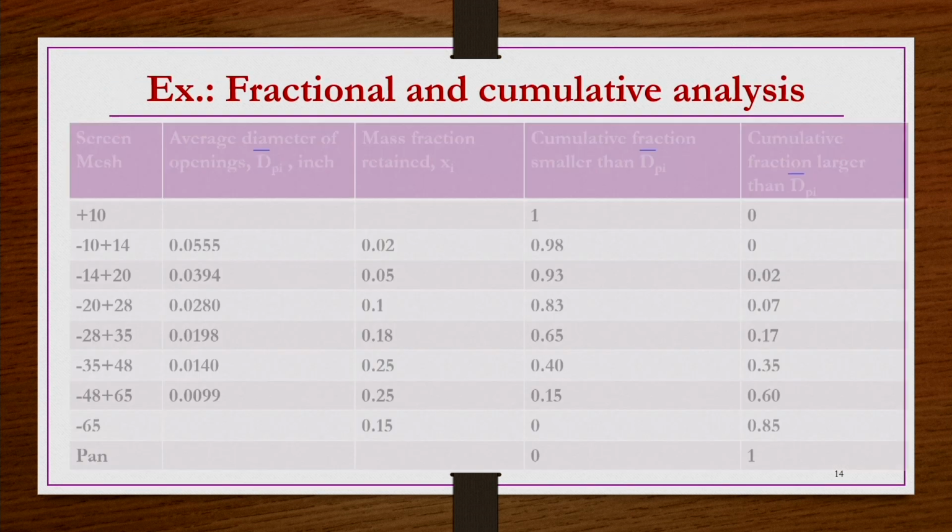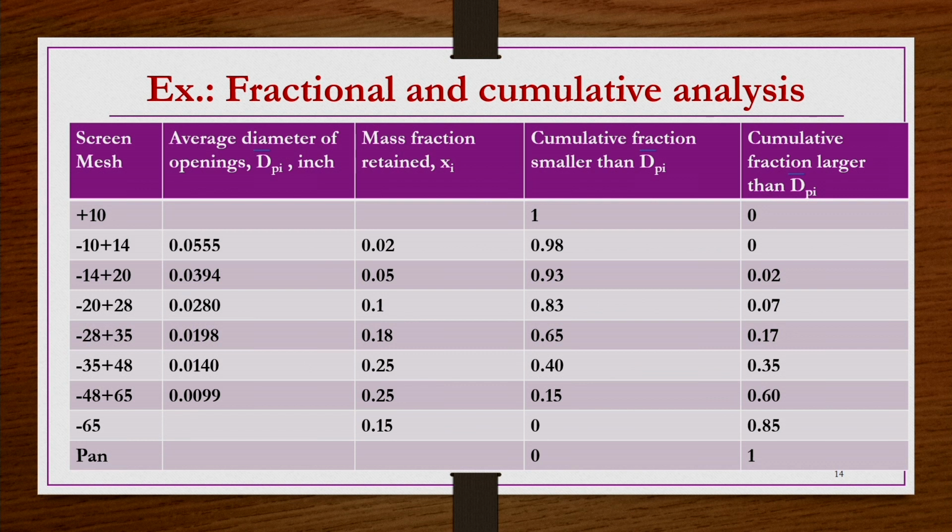Now, we take an example problem. Let us say fractional and cumulative analysis, we take this example problem. We have the mesh screens plus 10, minus 10, plus 14, minus 14, plus 20, like this; the screen openings, I mean mesh numbers, are arranged like that. At the bottom they have the pan, above it 65 mesh, above it 48 mesh, above it 35 mesh, above it 28 mesh, like that. At the top, 10 mesh is there, right.